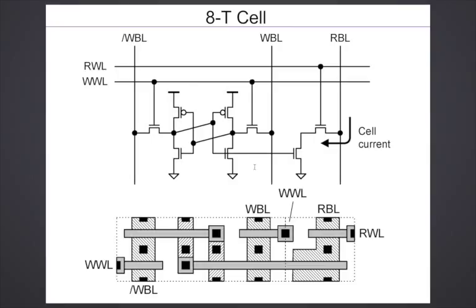Now, it's fine to have a solution which works down at very low voltages, but it turns out that people in industry just don't like to give out area. So SRAM is still largely dominated by the 6T cell, basically because of area. Unless it becomes a pain point where you say, look, I really have to run at a very low voltage. From a practical perspective, right now it is still 6T cells. So that shows the importance of area.